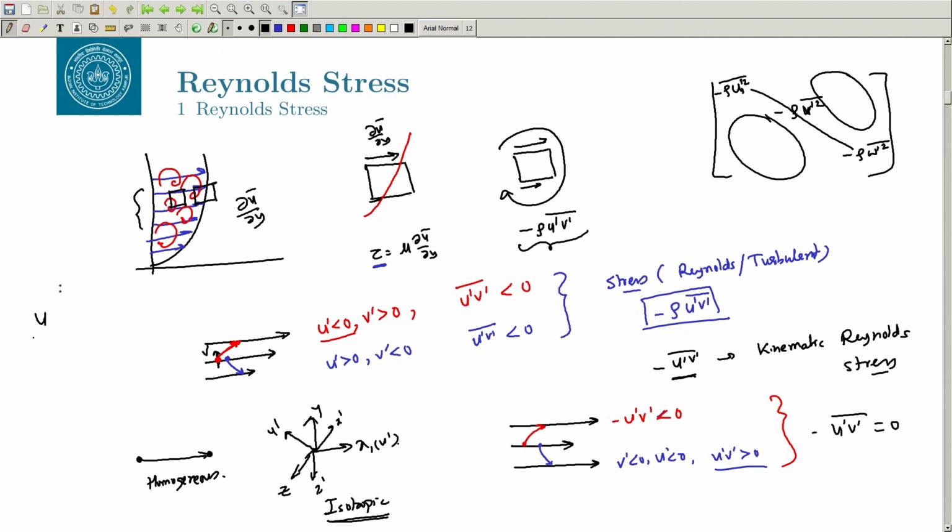In the incompressible flow you have u, v, w and p, these are the mean flow variables. You can write it as u bar, v bar, w bar and p bar because they are mean flow, but then you also have minus rho u prime square bar, minus rho v prime square bar, minus rho w prime square bar, and these are the isotropic terms, and then you will have minus rho u prime v prime bar, minus rho u prime w prime bar, minus rho v prime w prime bar. Okay, these are the deviatoric terms.